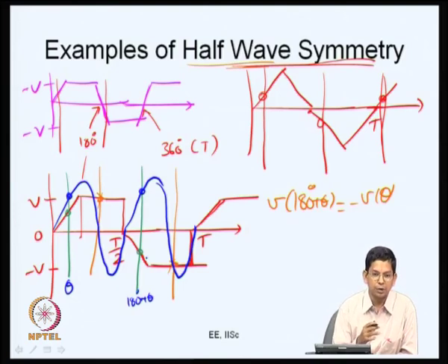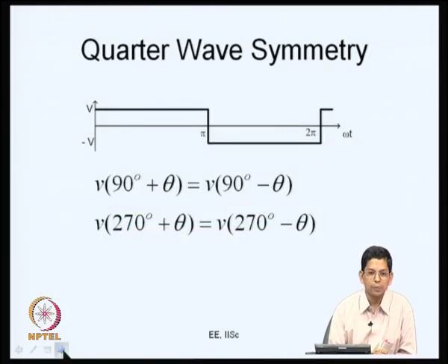It could be a little deceptive. At first sight many students generally tend to say, well, it does not have a half wave symmetry, but it has, and that is the property, and that is how we define half wave symmetry here, and it has the meaning of having no even harmonic. Now, let us go further.